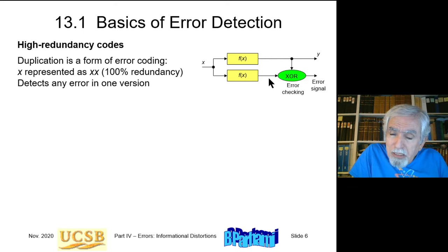If they're not identical, if they differ, so this does not have to be a single bit. If it's a single bit result, it's just a simple XOR gate. And if these are, say, words, then you XOR all the bits, and you expect to get all zeros. In other words, they should match in all the bits.